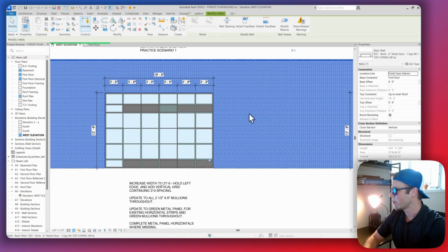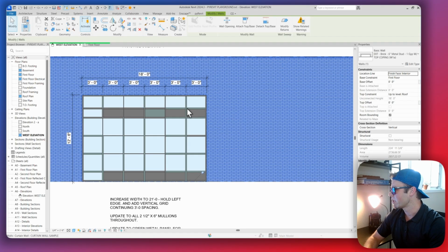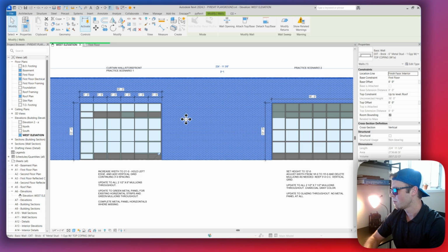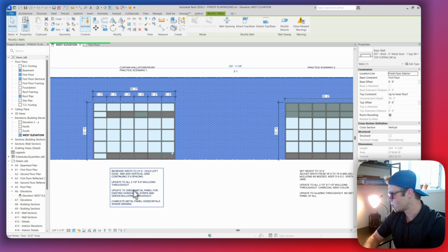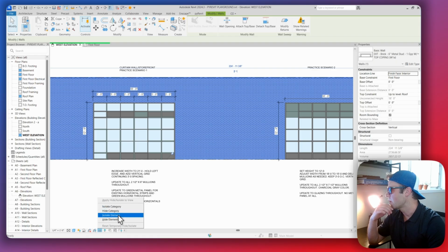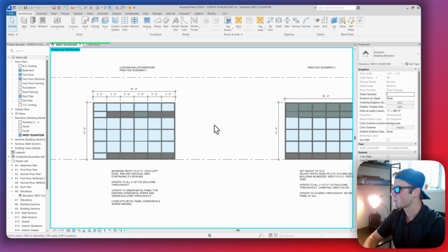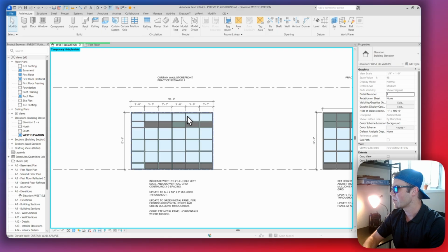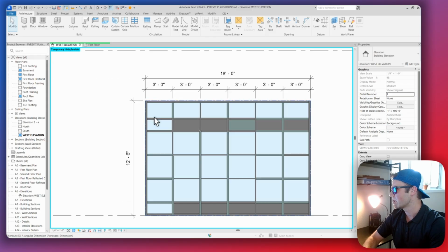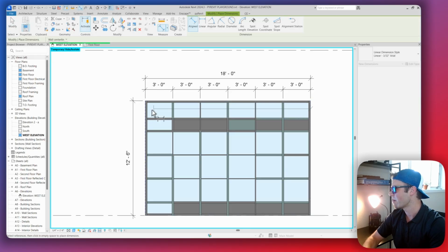And one other thing, when you're dimensioning things and working on curtain walls within a wall, like the brick here itself, we can use this tool where we select the brick wall and click on these glasses down here, temporary hide isolate, where we can hide an element temporarily. So if you've used that before, you know what to do, but you can hide that brick wall just temporarily so that you can more easily grab the edges of the curtain wall and not the brick itself, right? When you're dimensioning things, you're snapping to the grid lines and so forth.